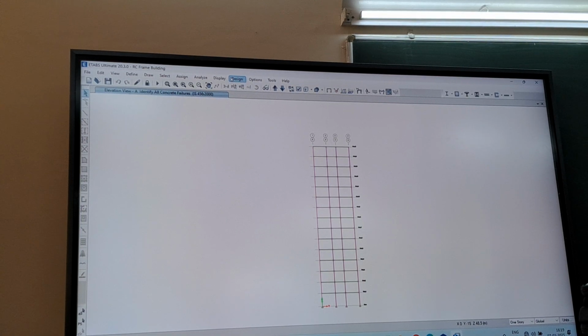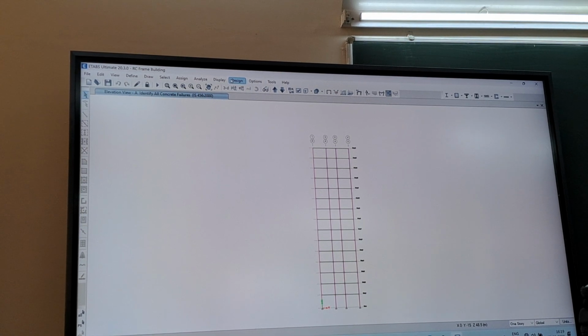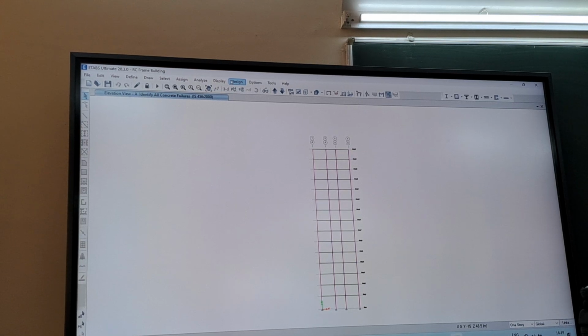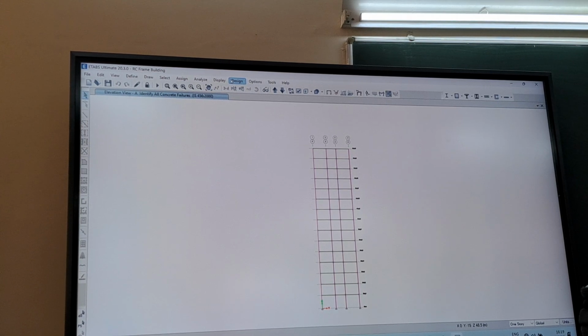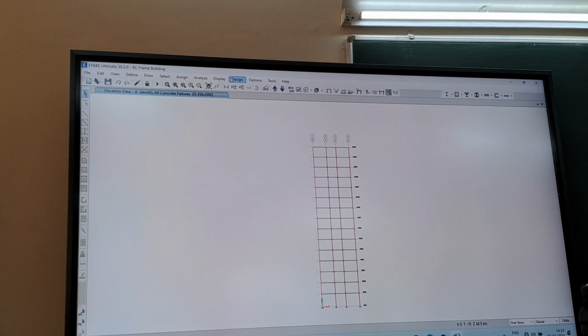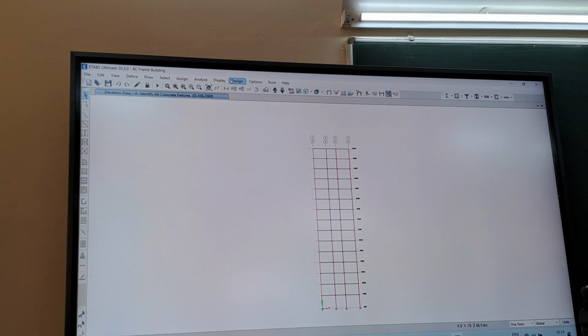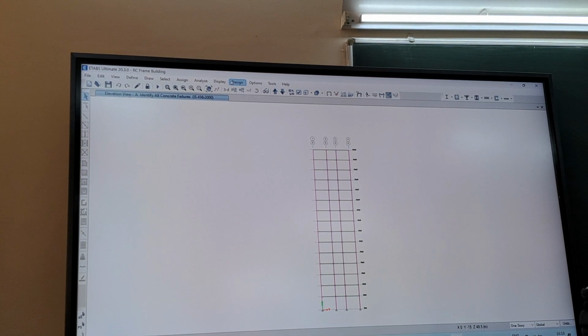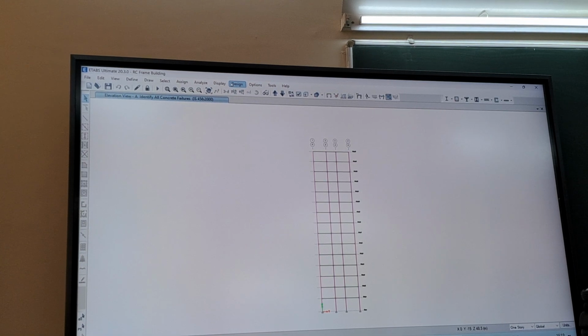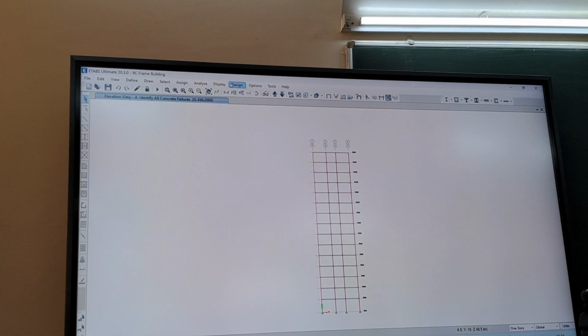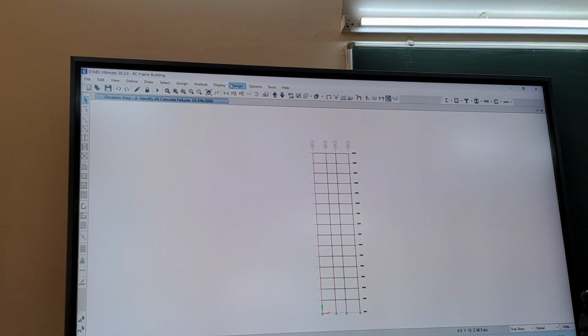But in general, what happens? As per the code, the maximum reinforcement percentage in a column is 6%. So we do not want reinforcement to be near 6%. 5% or 6% is not a very suitable amount of reinforcement. Normally, if it is between 2 to 3%, it is a very good estimate. So we will try to keep the reinforcement in that range, 2 to 3%.